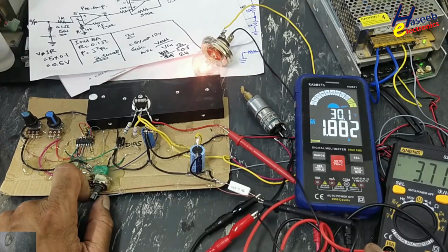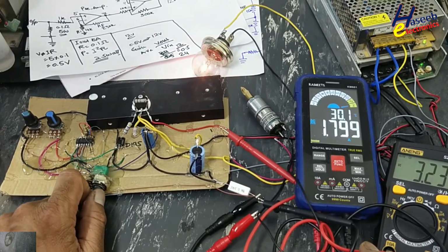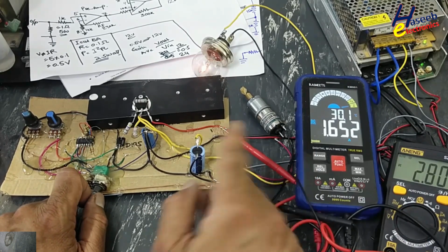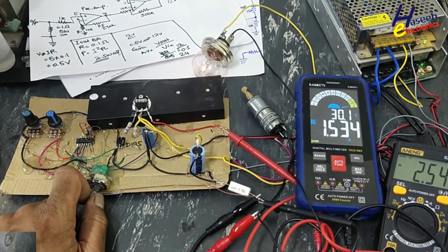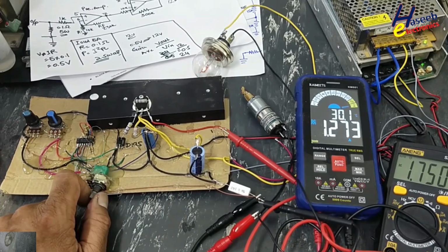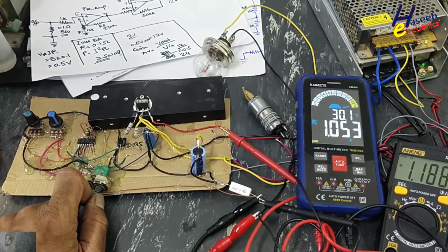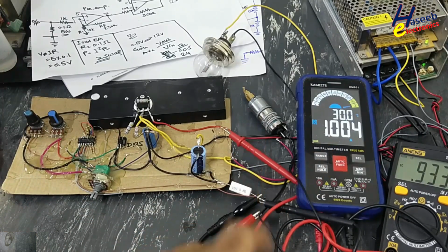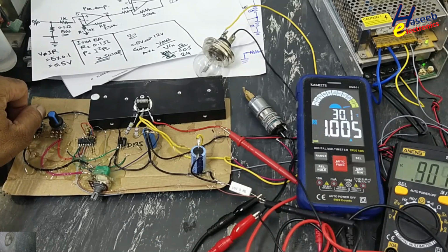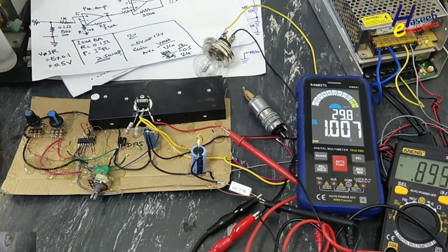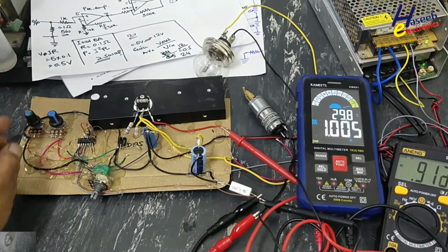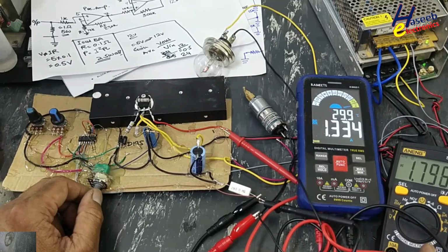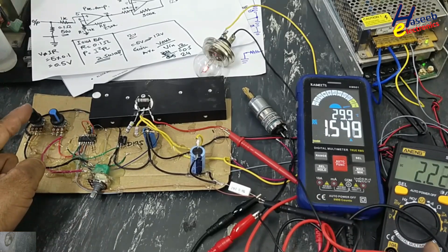Now if I decrease the current to 1 ampere, the voltage will drop as well, because we are in constant current mode. Now our power supply is in 1 ampere constant current. If you want to increase the voltage, it will not increase, because the system is in constant current mode. If I want to increase the current, the voltage will also obtain the setting from here.